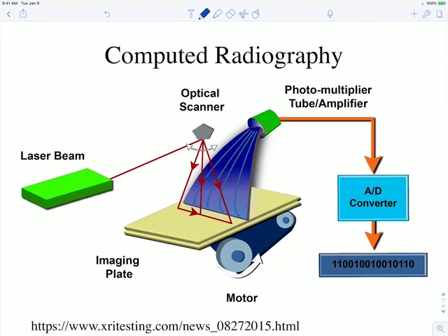But now, in this day and age, things are much more going towards digital radiography. So the first step is what's called computed radiography, where instead of having the film, you have an imaging plate which changes composition when it's exposed to the X-rays. But then you have a laser beam that comes through and scans it and sees where it was changed, and then you feed all those numbers into a computer. So you just have a computer image. Okay. Otherwise, you have to have this film and carry it around everywhere. And that's not very convenient.